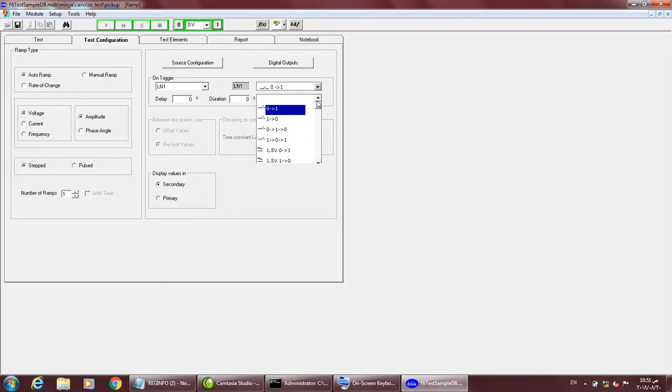Okay. And now see, there is another option as well. These are the potential free, as we discussed earlier. This is potential free and potential contact. If there is a potential contact, then there are two options here: 1.5 volt and 15 volt, and the status is the same, 0, 1, 1, 0. Four statuses are there, repeated. The only difference is that one is written 1.5 volt and the other 15 volt. These are two threshold settings.